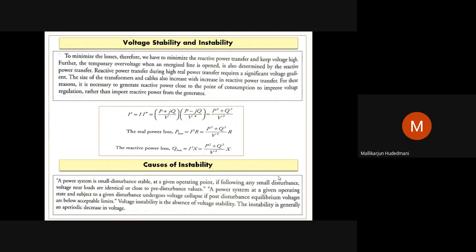So for that, voltage being one of the important aspects, voltage stability is to retain the nominal voltage within the permissible range by adopting suitable compensating mechanisms, suitable methods, such that voltage will not violate its specified bands. Therefore, it is to provide reactive power, because there is a vital link, a strong interdependency of voltage and reactive power, frequency and active power.